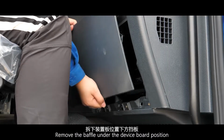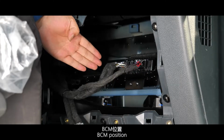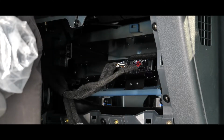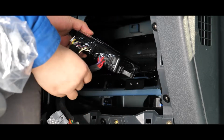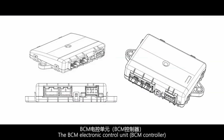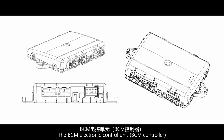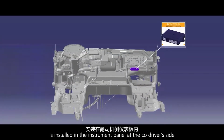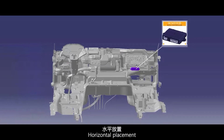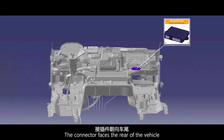Remove the baffle under the device board position. BCM position. The BCM Electric Control Unit, the BCM controller, is installed in the instrument panel at the co-driver's side. Horizontal placement. The connector faces the rear of the vehicle.